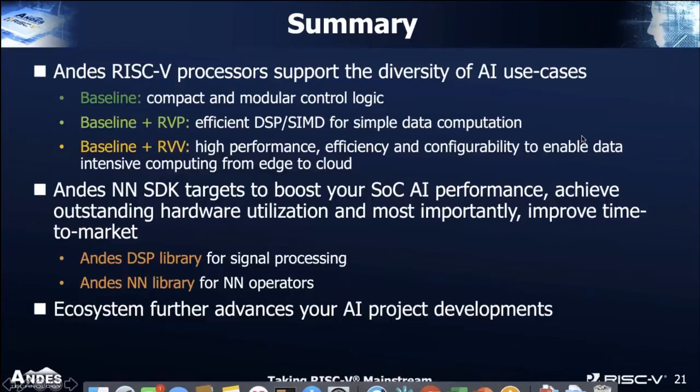We'll divide this into 2 perspectives. First, from the hardware perspective, the flexibility and programmability of RISC-V DSP and vector extensions is much better than a hardwired engine. A hardwired engine is fixed function and cannot be programmed. By using the DSP and vector extensions, we could support future AI technologies and achieve great performance efficiency.